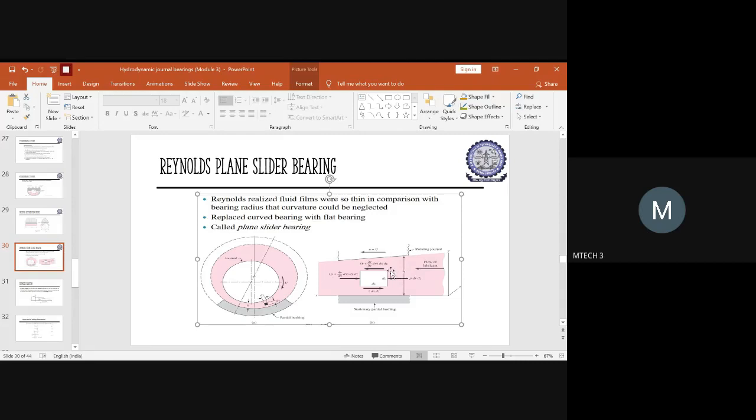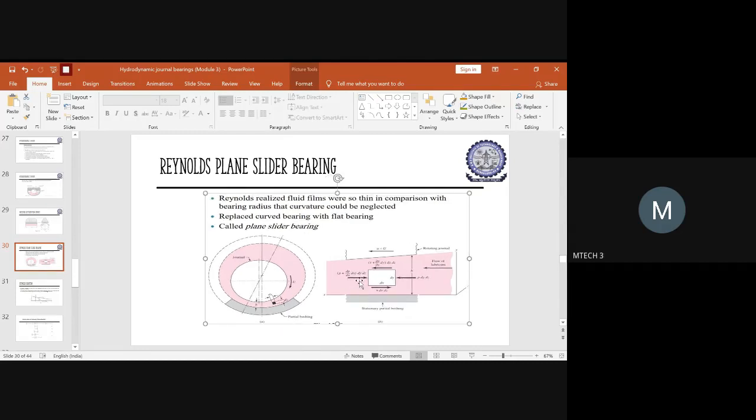And similarly here, when you are having a flow of lubricant in this direction, you'll be getting some opposite force which is coming in the backward direction. So while showing that, it will be in an opposite direction where you will show the pressure P plus the variation in the pressure with respect to the x coordinate into dx, and the whole thing will be multiplied by dy into dz. So this is for opposite direction.